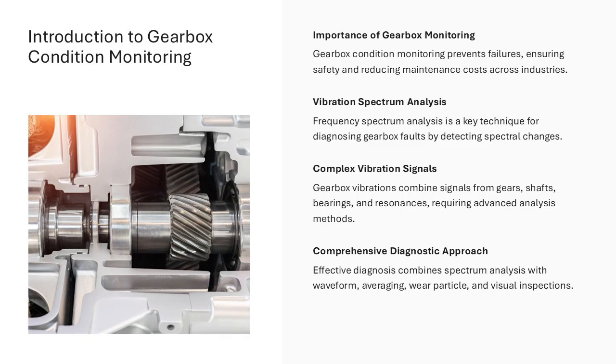From an engineering perspective, gearbox vibration signals are complex because they contain contributions from shafts, gears, bearings, and structural resonances. Unlike rolling element bearings, where specific fault frequencies are well defined, gear faults often manifest as changes in existing spectral components rather than the appearance of entirely new frequencies. Therefore, gearbox diagnosis relies heavily on trending, pattern recognition, and understanding how mechanical defects influence vibration modulation mechanisms.